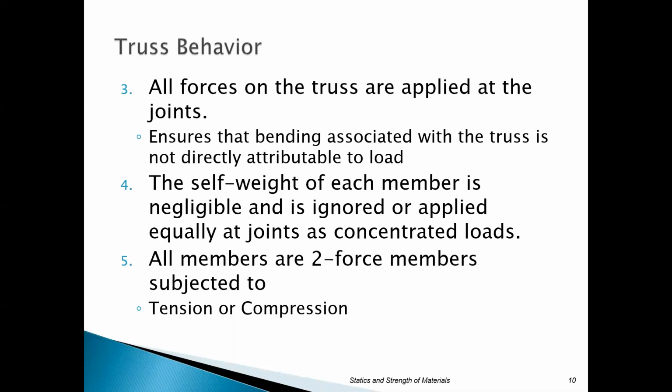The fourth thing, well, we do have five areas here. The fourth thing that we're going to look at is that the self weight of each member is negligible. So in other words, we don't worry about it when we are doing the analysis. What we're doing is saying basically that's all been applied through the loads.